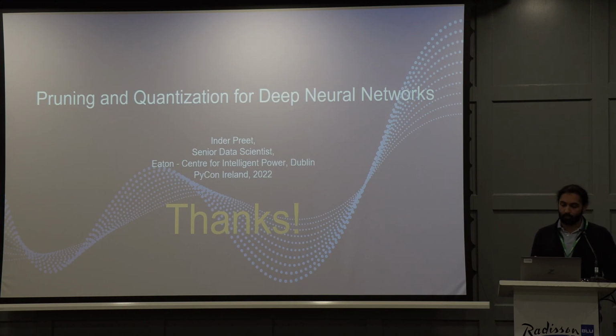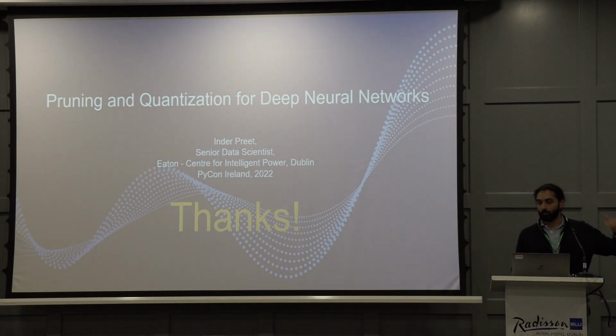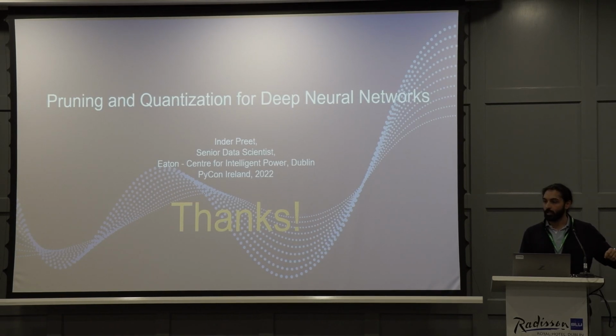Interesting point, that reminds me of another thing. Adnan Ashraf, who was also on the project, was doing his master's research back then. When we wrote the embedded code, we were using ARM's library for neural networks. There is PyTorch, and there is CMSIS by ARM for running neural networks on their embedded systems, taking into account how their processors are structured. He wrote embedded code using their functions, like their fully connected and convolutional layers, and then he wrote his custom functions. He found out that his custom functions consumed way less current than ARM's library.